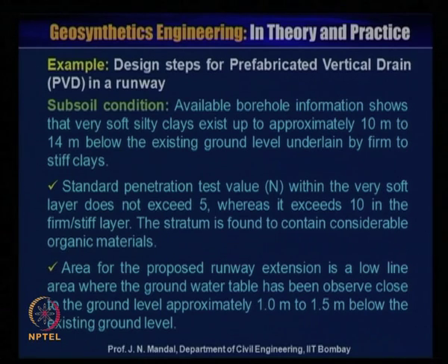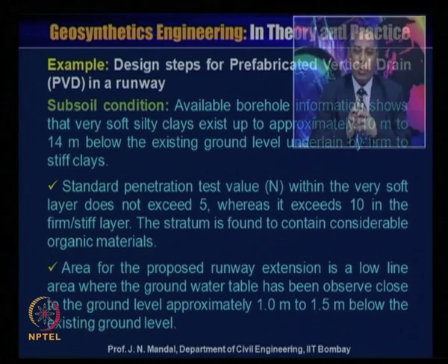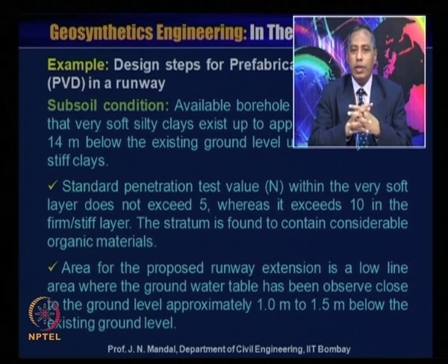Standard penetration test value N in the very soft layer does not exceed 5, whereas it exceeds 10 in the firm and stiff layer. The stratum is found to contain considerable organic material.